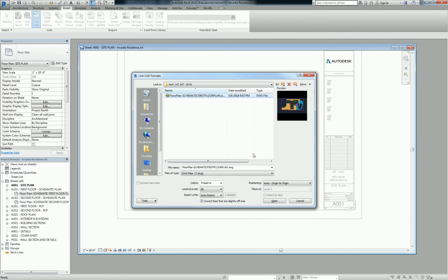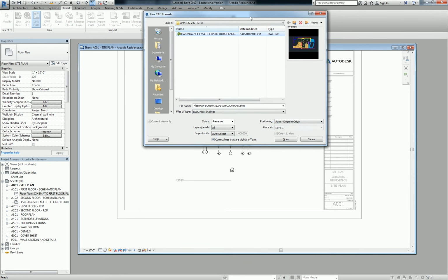and this is the file that we're linking, and I want to call out some information down here. So first and foremost, what I mentioned about it being connected to the view versus being an actual three-dimensional element, this is the checkbox for that. Current view only and orient to view are the ones that assign whether or not it's only going to live in this view or if it's going to be a three-dimensional element. So anyway, we're going to switch our colors to black and white.